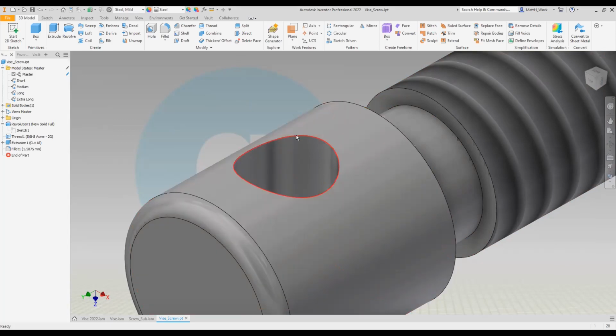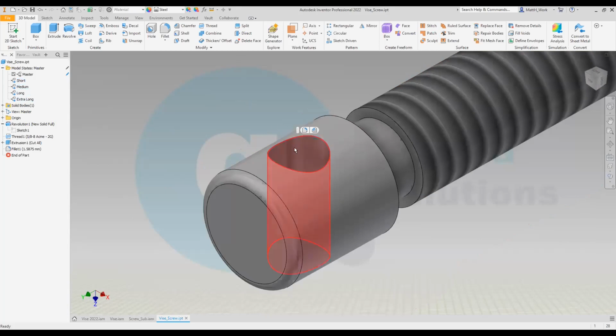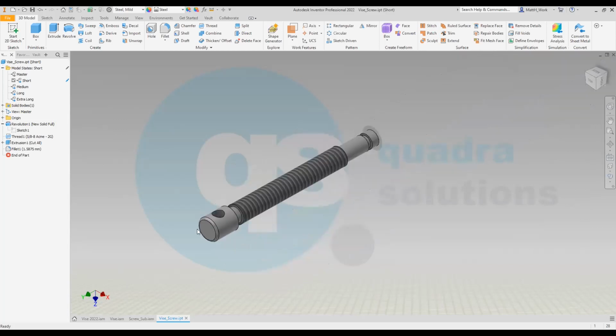Factory scope. If I put a chamfer on that edge, every size of this component will have a chamfer on the edge. Member scope, if I had the chamfer on this component, which is currently set to, let's say, short, it wouldn't exist on the medium and the long version. With an iPart and an iAssembly, if you delete a feature with Inventor 21 or prior, it actually suppresses it if you're on member scope. New to 2022, which is probably Autodesk making it work like it should have done, but it will change everybody's muscle memory. If you delete a component or a feature, it gets deleted across the board. So a little bit of a gotcha on that one. My muscle memory says if I'm on member scope, I can delete a feature and all it will do is suppress it for this row. But going forward, if you delete a feature, it will delete it properly. So I've got a couple of sizes in there.